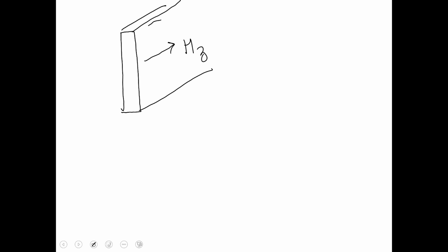This is equivalent to the H1 we had, and thus the normal which has to be defined, if I was using that equation of N cross H which has been derived, would be a normal coming from the dielectric into the conductor. This would be the normal on that component. On the other plate, on the other side, now I am sitting here, Hz is sitting here, the normal would have to be on the conductor pointing outwards. So that depends on how we define the boundary condition specifically.